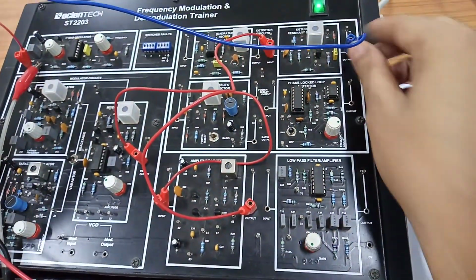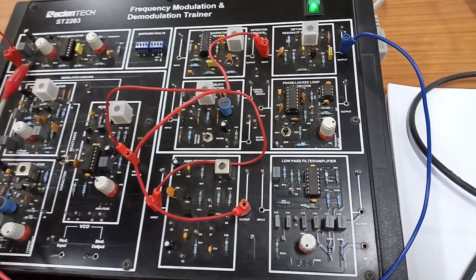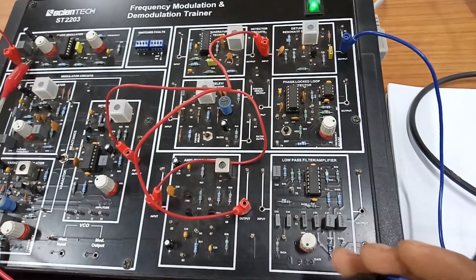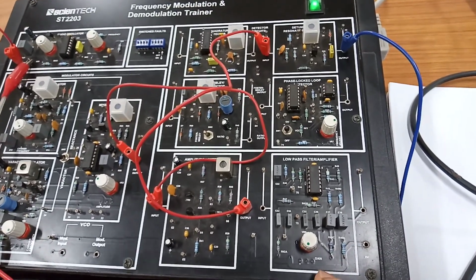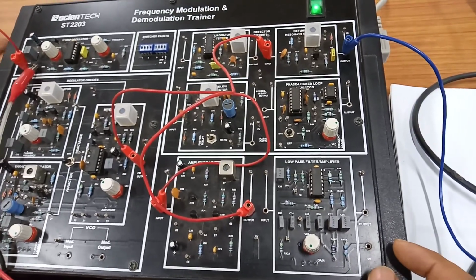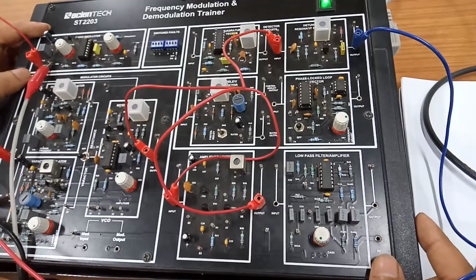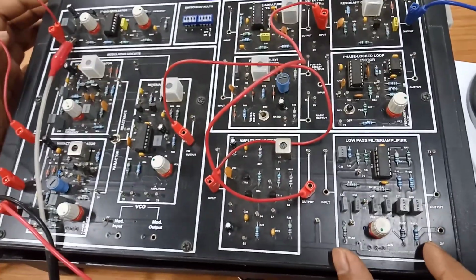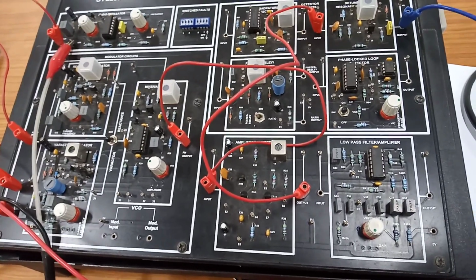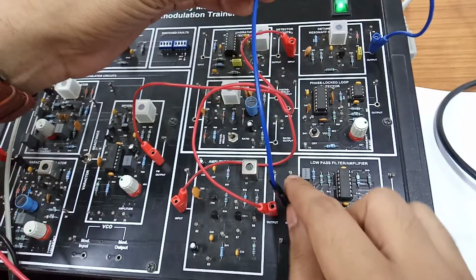Now I am connecting this output to a low pass filter, because whatever audio signal we have given over here, if we are using a low pass filter, the higher frequencies are getting stopped and we are getting the lower frequency, the audio signal frequency that we have transmitted where the information is. So the wave will get demodulated as the audio oscillator generates a signal of audio frequency where the information is. So we are using a low pass filter to pass that particular audio signal and clip off the higher frequencies due to the carrier wave. So I am going to connect the output of the detuned circuit to a low pass filter.